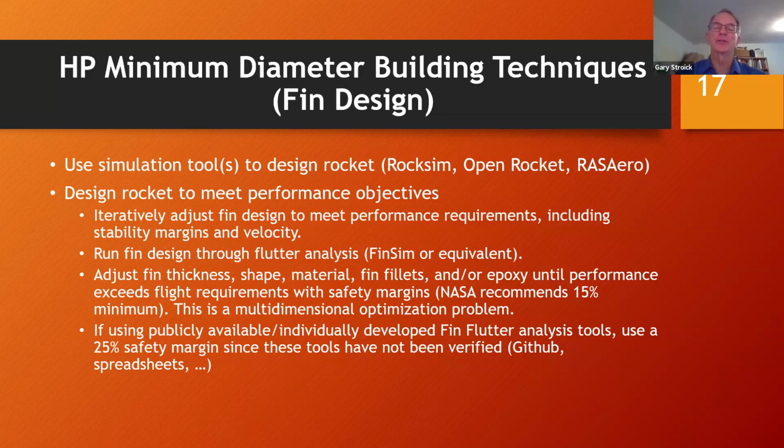If you're going into those velocities when you're flying your rocket, just be aware that the projected altitudes may be a little lower than what may actually occur in the flights, and the velocity data will be off as well. RASAero is also a free tool online that models rockets not only in the subsonic range, but transonic, supersonic, and hypersonic ranges.